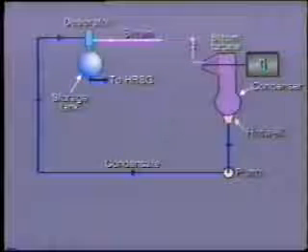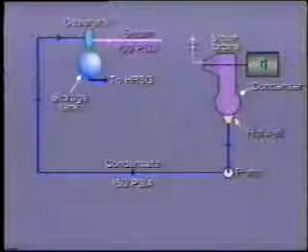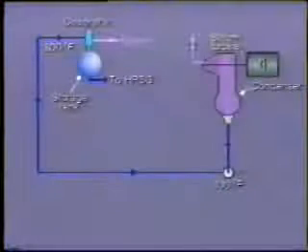We have already noted that typically the steam pressure in the de-aerator is about 100 psi or 7 bar. So we would expect the condensate pump discharge pressure to be about 150 to 200 psi or 10 to 14 bar. The temperature of the condensate in the hot well will normally be around 100 degrees Fahrenheit, 40 degrees Celsius. In order to increase the cycle efficiency, it is usual to increase the condensate temperature to about 300 degrees Fahrenheit, 150 degrees Celsius, before feeding this into the de-aerator.